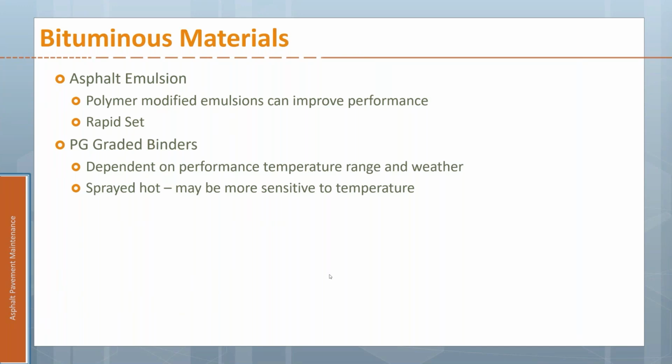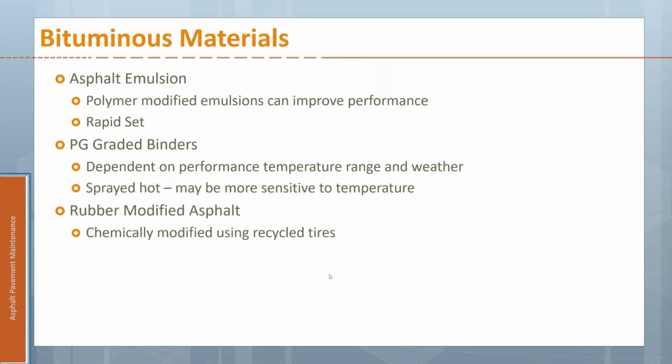So depending on your temperature range, your weather, it's a little bit more sensitive to things like temperature, but also if you have any moisture or dampness on the roadway, that's going to be an issue. But it's very particular on temperature and getting it sprayed down correctly without clogging up equipment and things kind of going wrong. But it's a higher quality binder. You get more oil, so sometimes you do get a much better performance out of it overall.